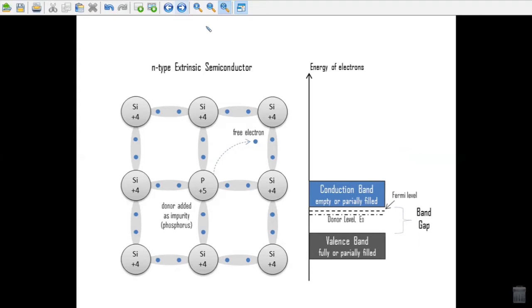However, frequently some known impurities are introduced intentionally to impart specific properties to the host material. The resulting semiconducting material is known as extrinsic semiconductor, whose properties depend on the type of impurity introduced into the host material. For this purpose, normally a few parts per million of suitable impurity material is added to the melt during the growth of semiconductor crystal.